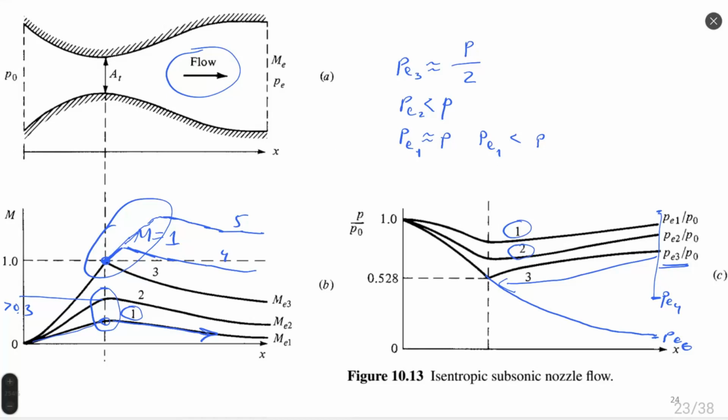There is a question from Louise. Can the opposite also happen, where the flow starts and ends in a supersonic regime? Yes, flow is isentropic. This nozzle is isentropic. Model of flow is isentropic. So if we have a reverse flow, not in this direction, we have flow in the opposite direction, it can be going in absolutely the same way.